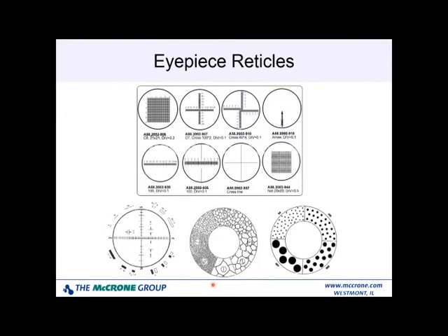On measuring microscopes, or on microscopes of any sort, you can put in eyepiece reticles for field of view measurements. These are very good for simple length measurements. They can be configured in metric or inch specifications. You can have grid patterns, you can have scale patterns, you can have scales on cross lines, or you can have specialty reticles to put into your eyepieces.